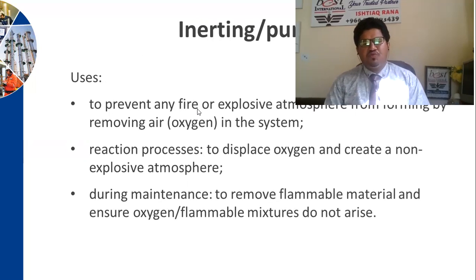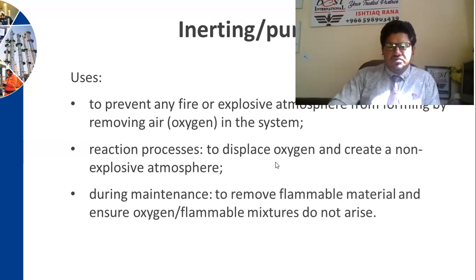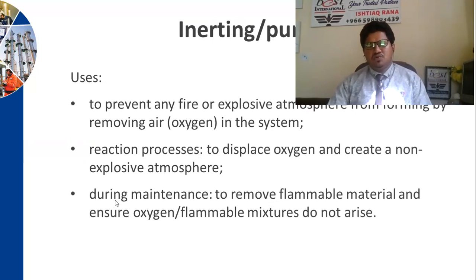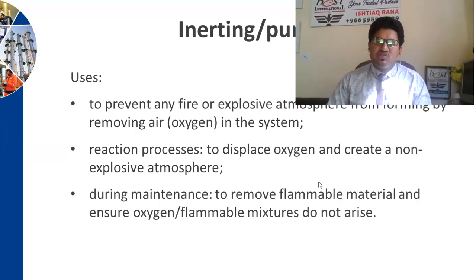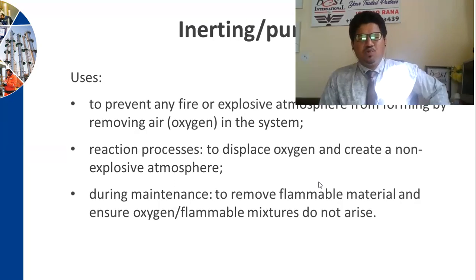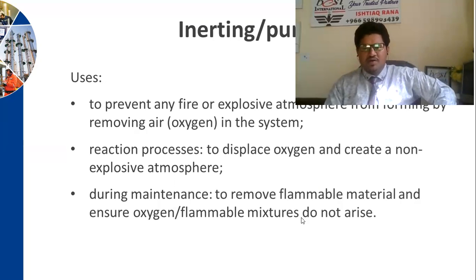Inerting or purging is used to prevent any fire or explosion by removing air and oxygen from the system. Reaction processes displace oxygen or create a non-explosive atmosphere. That's why for confined space and hot work, purging, cleaning, and steaming, like water wash or steaming, or even purging by using nitrogen, is important, because we need a non-explosive or non-hazardous area. So during maintenance, remove flammable material and oxygen so that flammable mixtures do not arise.